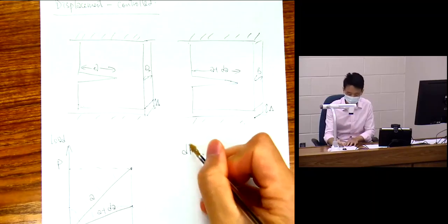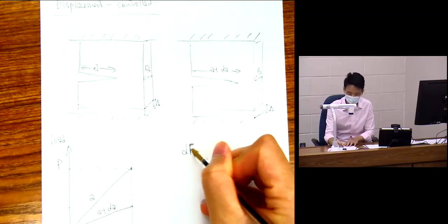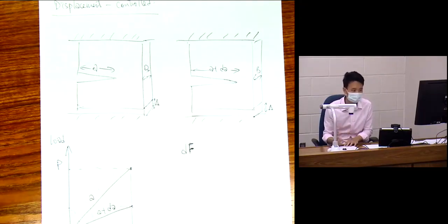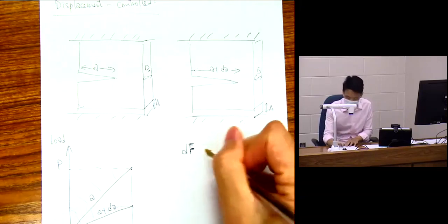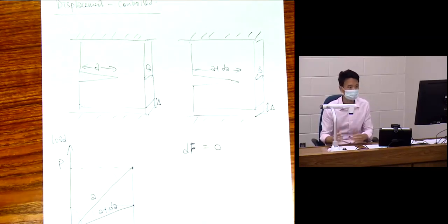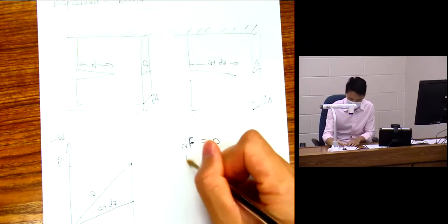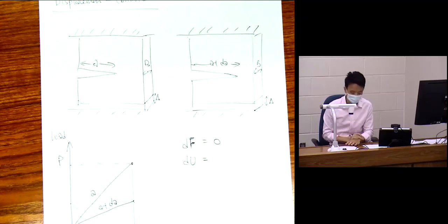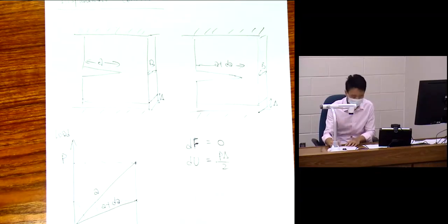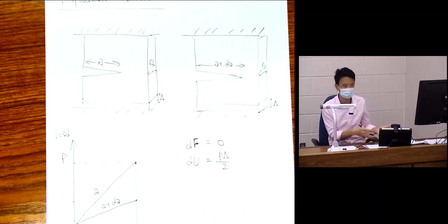Let me show you a different way. The change in work done between these two is 0. Okay, there's no change in work done, because the crack moves a little bit more but there's no change in delta. There's some change in the elastic strain energy, and you can verify this, because I'm not going to go through it again, but you can go through the same process I went through with you previously.